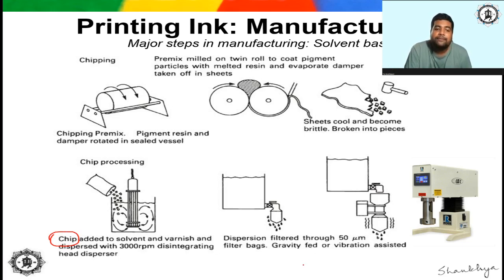Once you are adding this pigment within the solvent along with the resin and additives, etc., then that needs to be dispersed, not with the dye stuff but with the pigment. In order to do this, the entire chamber within which the material has been placed is shaken or vibrated vigorously. Due to that agitation, the pigment starts to get dispersed within the solvent of the vehicle component in the liquid ink. So this is a major difference in production of solvent based and paste inks actually.